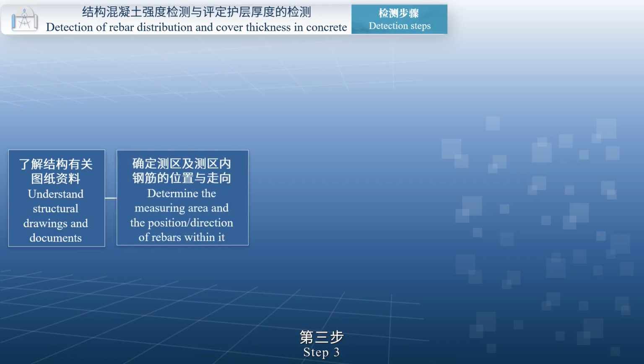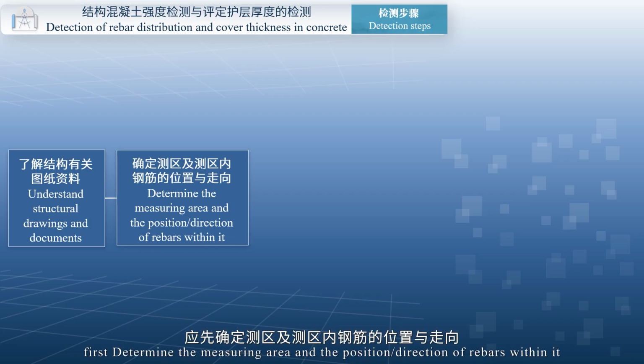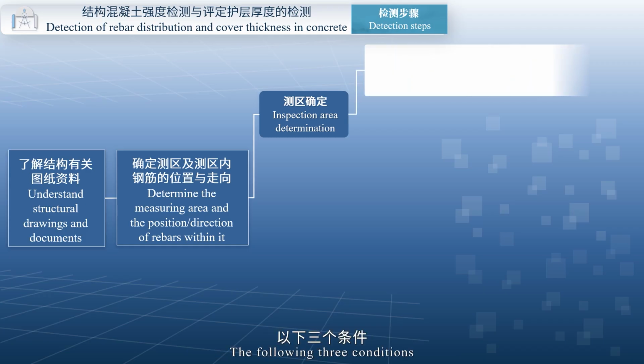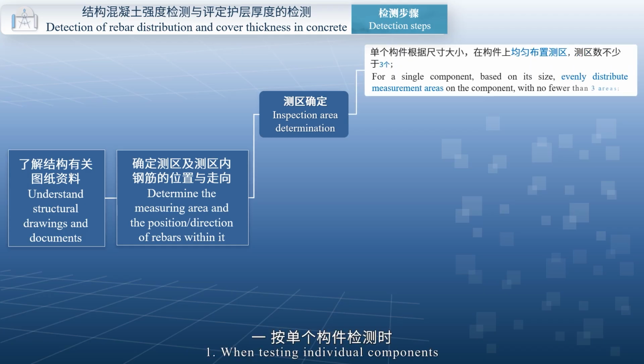Step 3: before measuring the cover thickness, first determine the measuring area and the position or direction of rebars within it. Measurement area determination must satisfy the following three conditions. First, when testing individual components, evenly arrange measurement areas on components according to size. The measurement areas on each component should not be fewer than 3.